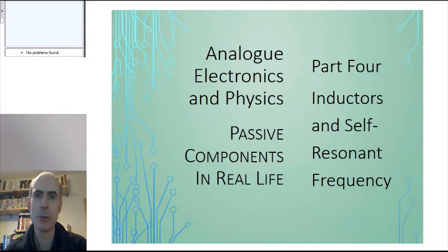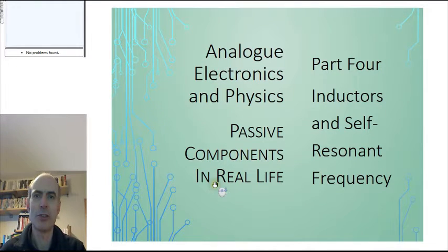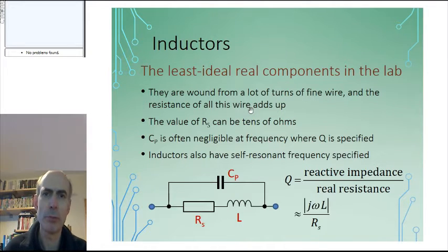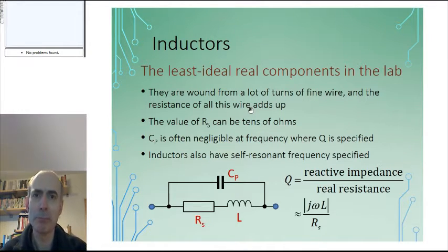In this video, I want to talk a little bit about inductors and the properties of real inductors and how they differ from the ideal inductors that we use in simulation models. It's worth noting that inductors are by quite a long way the least ideal real components that we will meet in the lab. It's always a good idea to avoid using an inductor if at all possible.